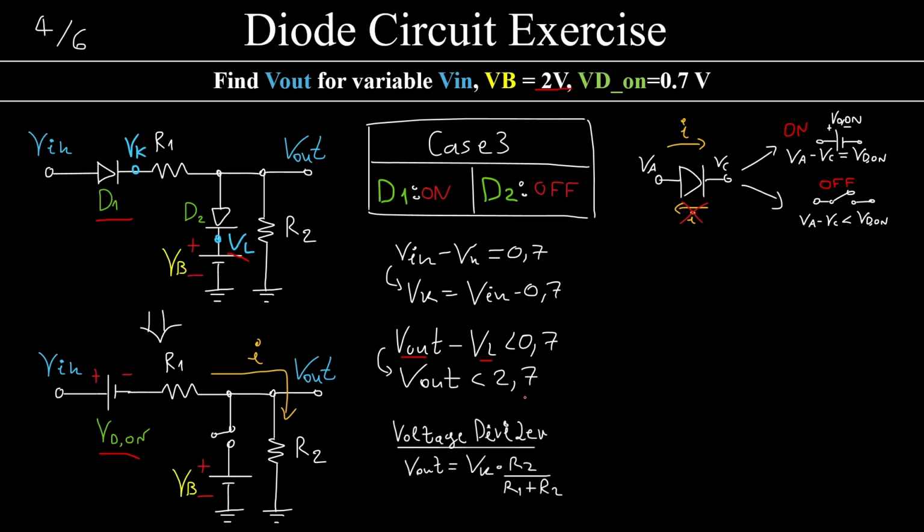Now, both of these conditions I suppose are true, and because the current flows from this point all the way to the ground, and we don't have any of it flowing through this node over here, that would mean that this is nothing but a voltage divider from circuit theory.